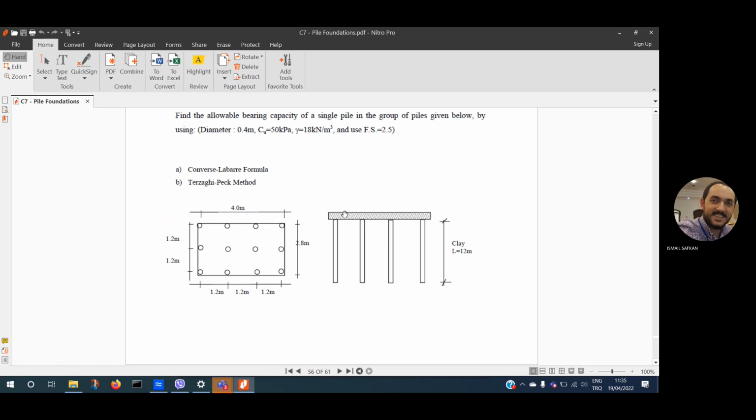The reason for that is usually we construct those piles a bit higher in height, and the contact material, the soil material, will be a fill material. That's why it will deflect and settle with time, and you will have no contact with the raft and the soil underneath, okay? But because of the compatibility equations, remember from the strength of materials, compatibility conditions, you will only have those piles resisting the raft, not the soil underneath.